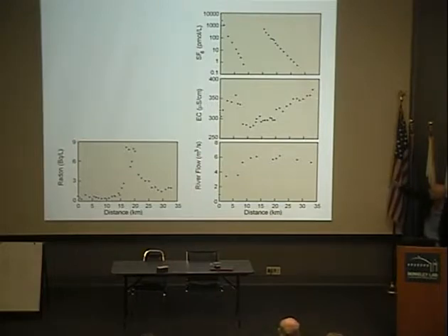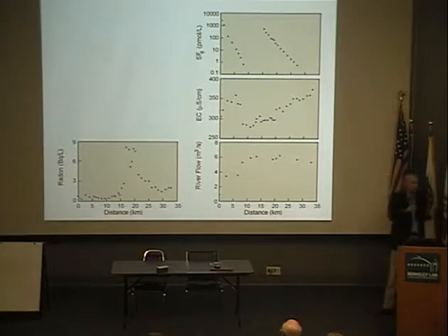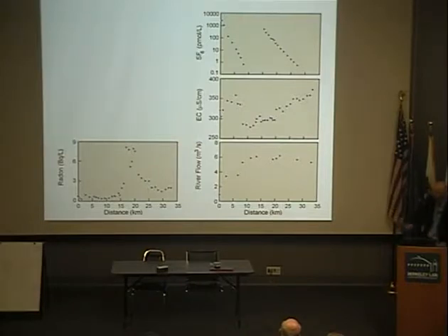This is the electrical conductivity that I showed you before. There are a couple of tributaries here, and then that increase in EC. This is the SF6 data. So I threw these diffusers in 2 locations, one up here and one up here, and then measured the concentration downstream. It's on a log scale, so it plots linearly on a log scale, which is consistent with the exponential decrease in concentration. And these are some river gaugings we made at a number of different points along the river.